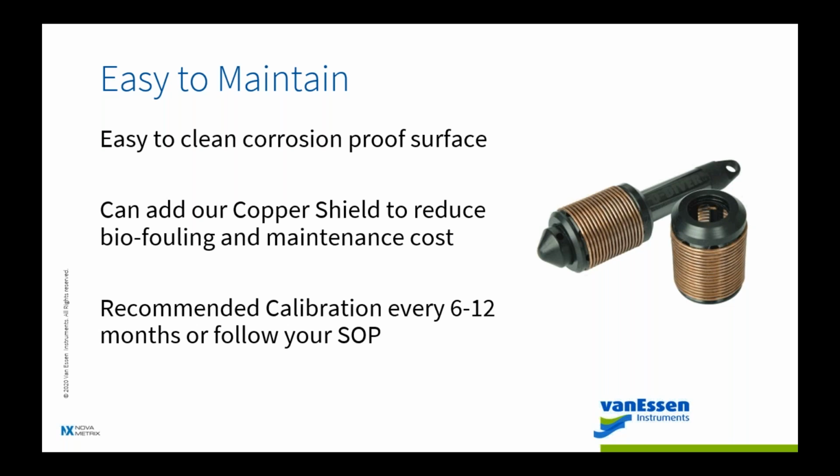I can't remember specifically what it was, and it was virtually rendering the conductivity measurements useless because it would plug it all up. After they cleaned it out with a pipe cleaner and put it back in place, they knew they had to be back out in 6 weeks. But we introduced these, and it has been about every year that they need to visit. So there's a significant change in their number of visits, and they're quite happy with that.